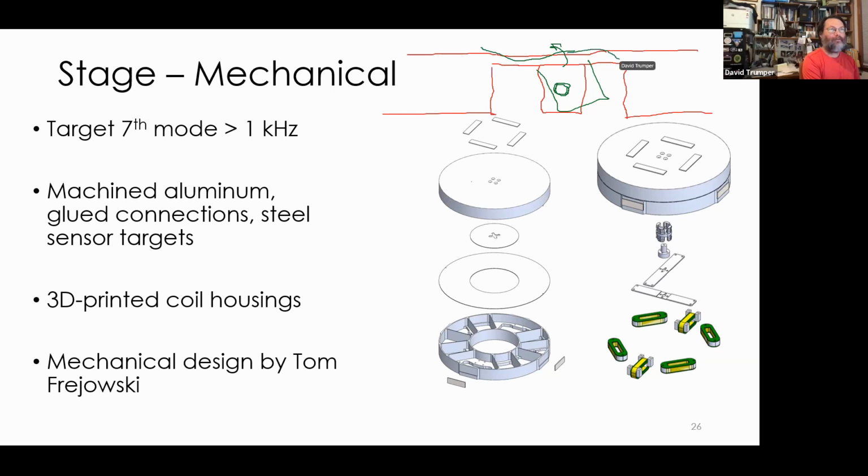You get sensitized to cantilevers. They're a beginner's favorite design element, but they're really bad in terms of dynamics. A little plate, whereas things in tension, think of a piece of paper, it's got no bending stiffness, but its tensile and shear stiffness is very high. So if you can get skins in tensile stiffness, with very little extra mass, you can change the modes a lot. That's kind of a generic lesson.